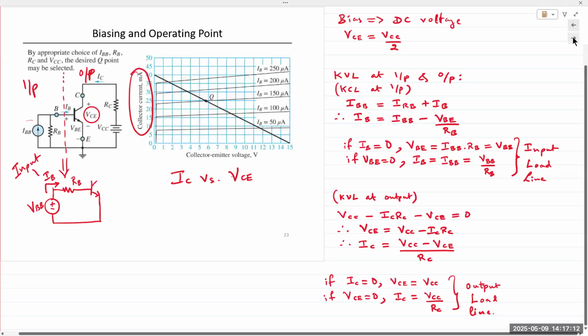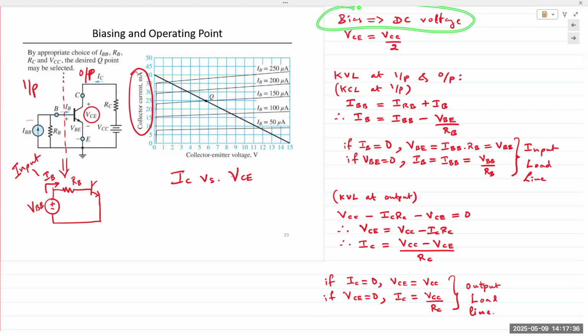Okay, so in order to set the operating region and hence the operating point, we apply DC voltages. DC voltages are set or applied to our devices, and the procedure is known as biasing our device or biasing our circuit. So biasing is basically the application of an appropriate DC voltage to generate an appropriate DC current based on our application.